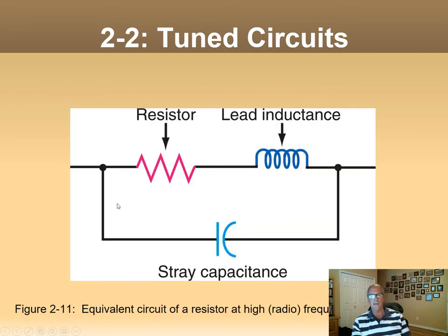So this is what it looks like in real life with high frequencies. Obviously at low frequencies, the capacitor becomes an open circuit, so it goes away. At low frequencies, the inductor, what does it do? It becomes a short circuit. It's just a wire. So they both go away and you end up with just a resistor.